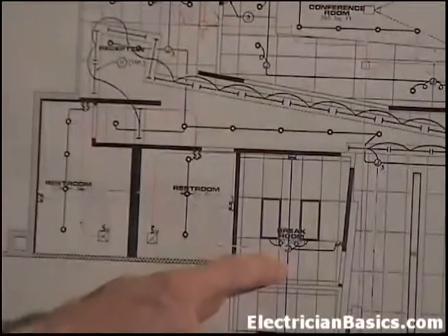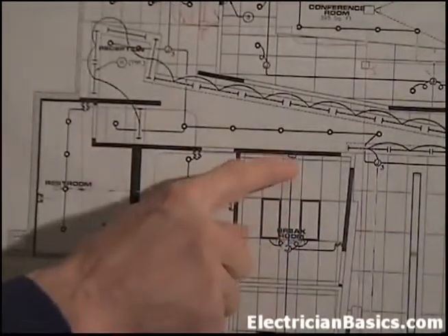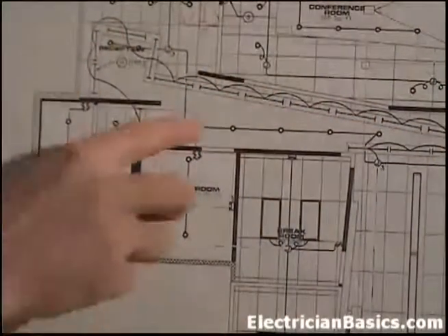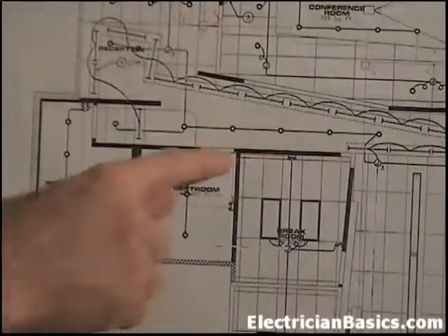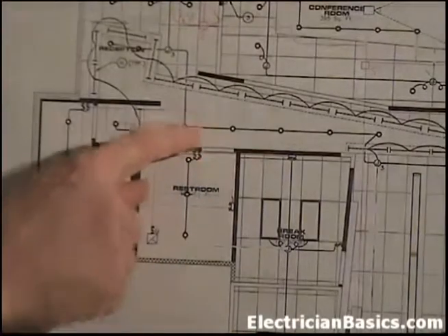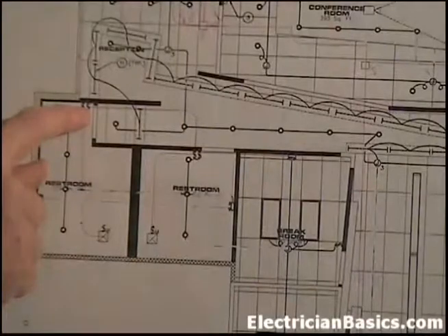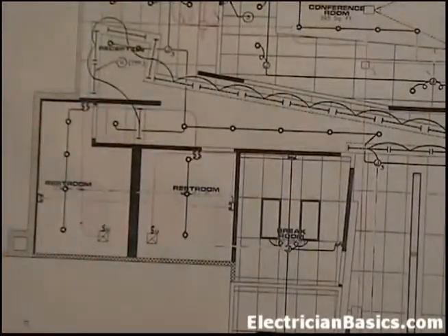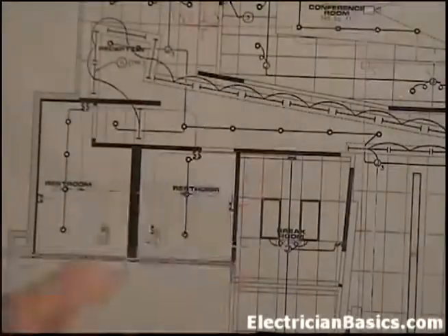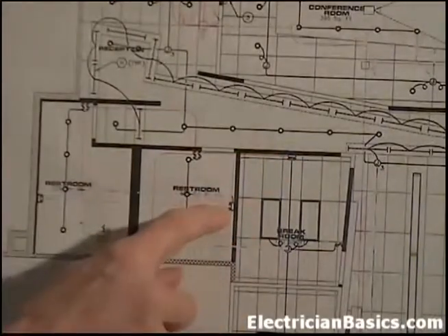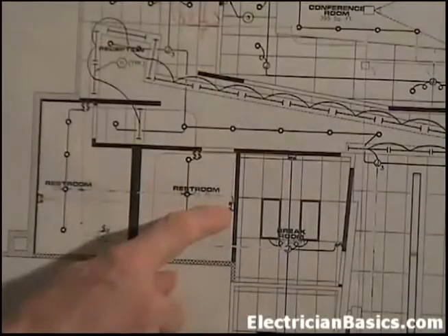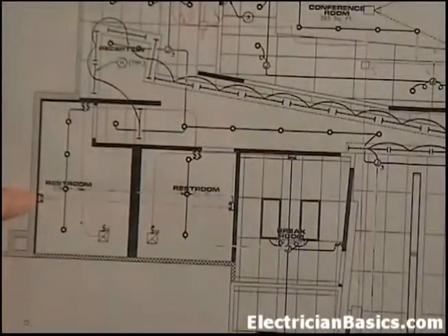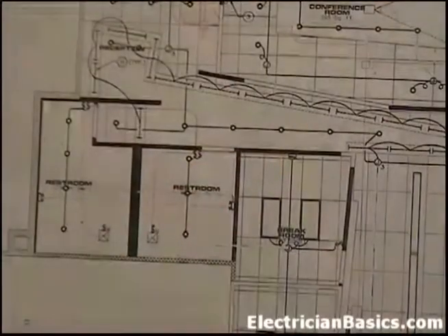So here's what we did. We went ahead, let this go to the emergency light. We ran a conduit into this switch. Now remember, this is all hard lid here, so we can't have any junction boxes in the ceiling. Okay, but we have a hot leg here. We're going to run to here, into this wall, okay? So the junction box is here and here, so we get to each of these switches, so we're good with those. Okay, now, we also came out of here with a hot to this emergency light, and that was circuit 1. And we came out of here across to this emergency light, and that's circuit 1. These are on the constantly hot, so that takes care of those.